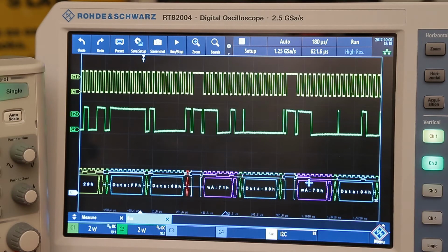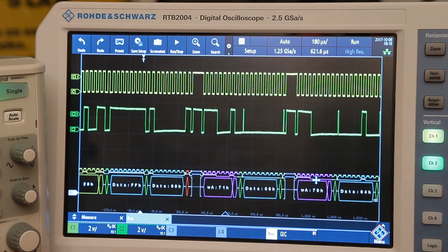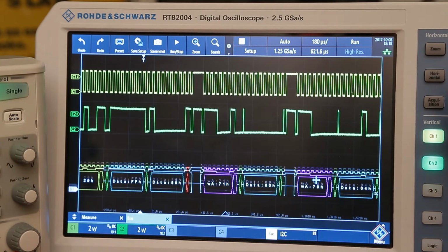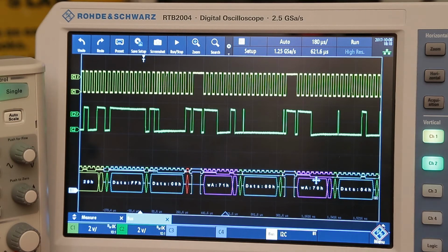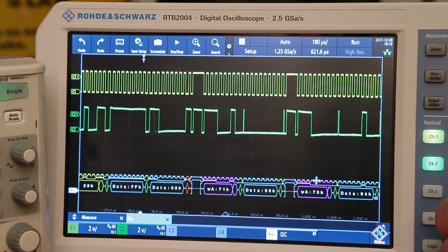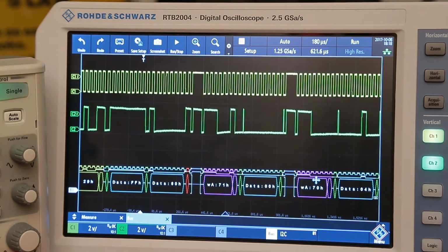On this scope, because I'm selected on the protocol, I can move the protocol either physically on the screen with the mouse or with the position knobs, which are indented. What I can also do, which I can't do on the Keysight, is to change the width of that, so it's quite sophisticated, the display. So I'm making that narrower, making that larger, and that's quite useful, particularly when you're showing